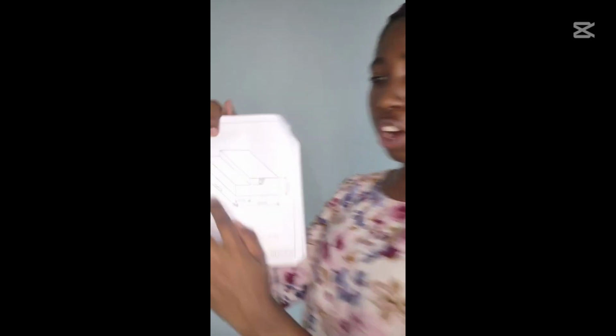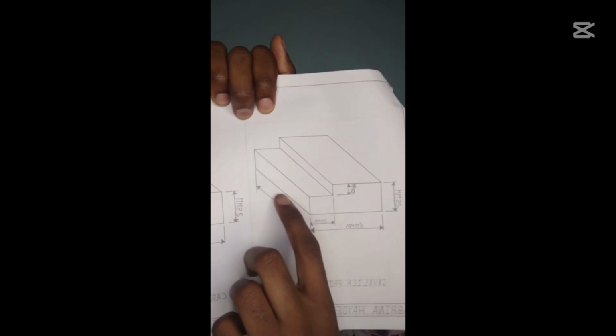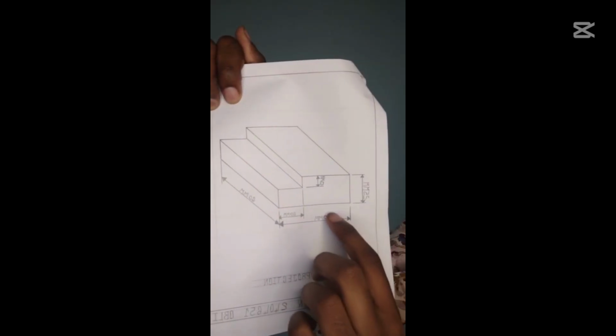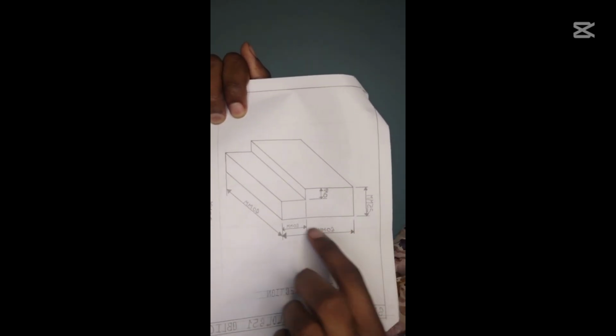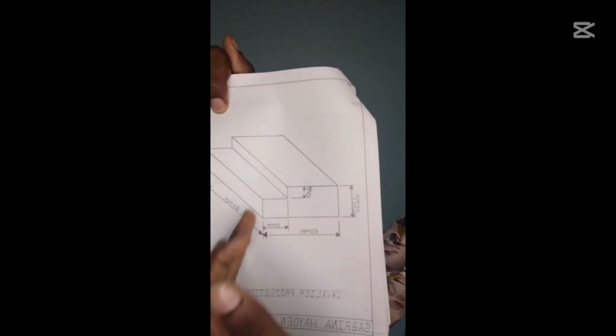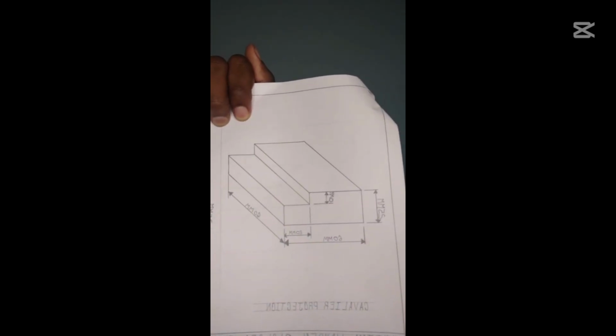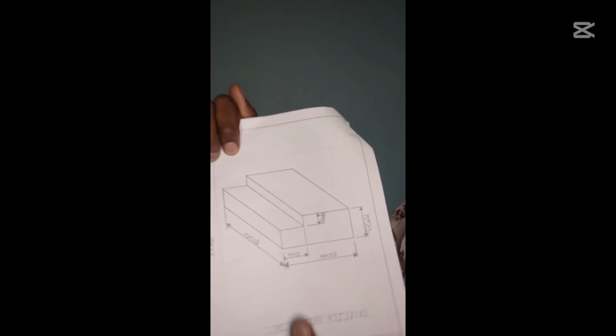And then you have all these lines going at a 45-degree angle. So that's the other thing. In oblique projection, we do not use a 30-degree angle and stuff like that. If we are going to do an oblique projection, you're going to need your 45-degree set square only. Because we use 45-degree lines, which are going in this direction. Then we're going to need our horizontal lines, which we would call 180 degrees, and then our vertical lines, which would be 90 degrees.